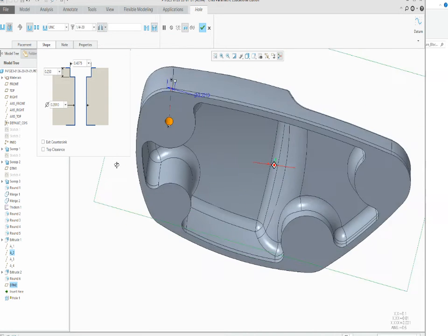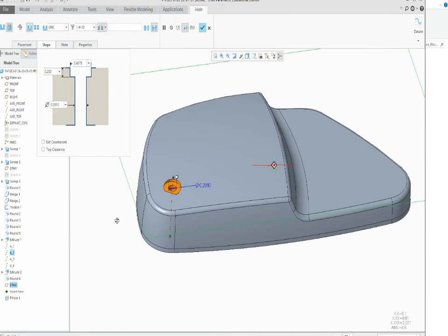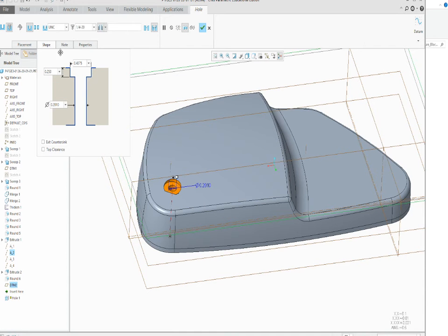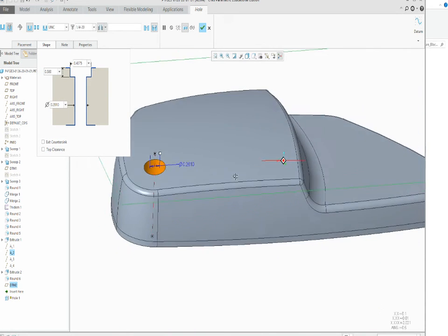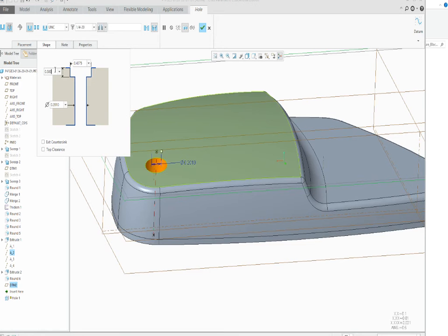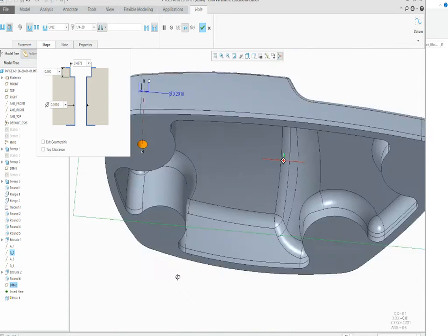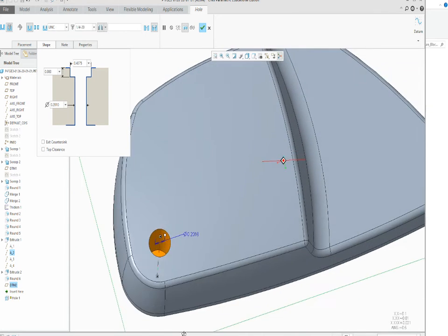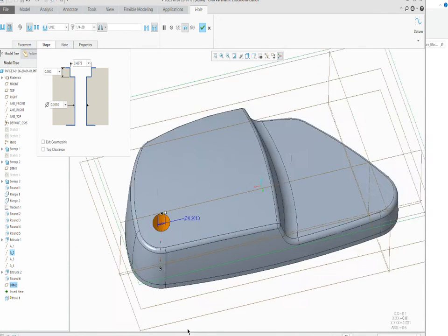Now you just got to make sure that you're going down far enough into the part. So at this time on this cover, 1/4-20 looks good, and I'm going to go 0.5 into the design. So that one looks pretty good. I'm going to go even farther. So let's go 0.9 into the design. If I go 0.9 into the design, it looks pretty good, and it sinks down far enough on the design.